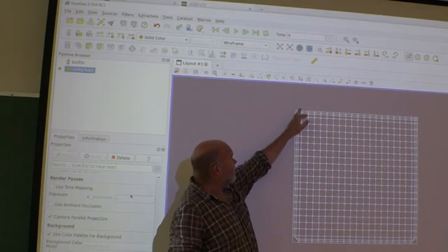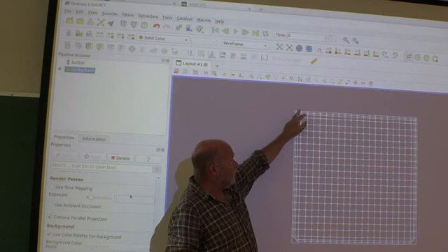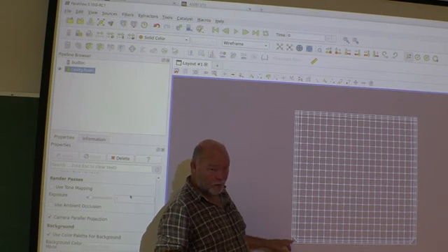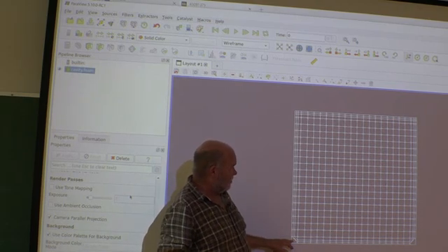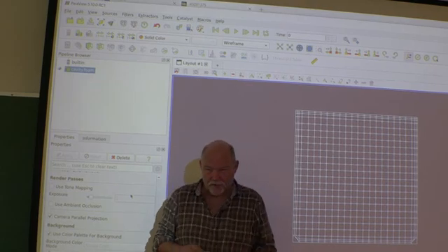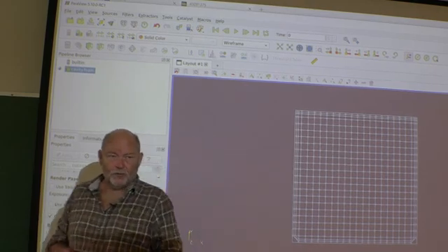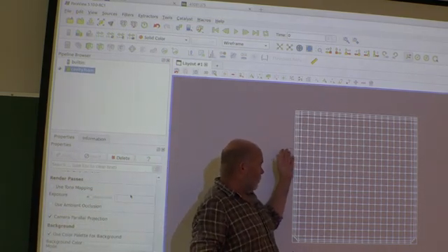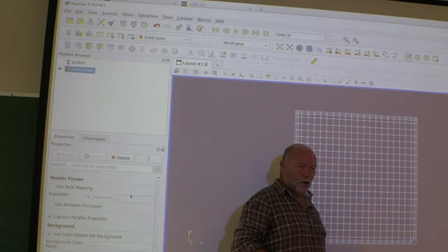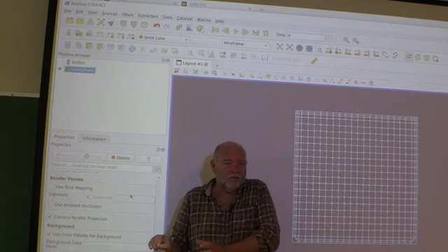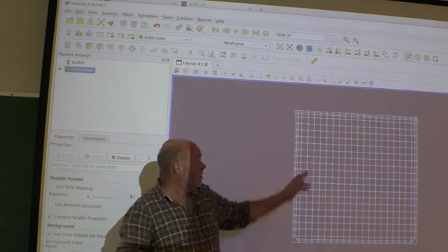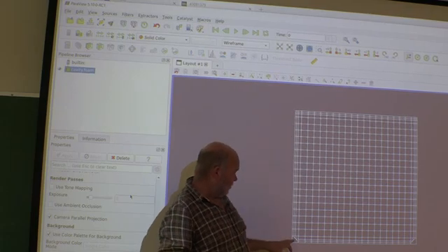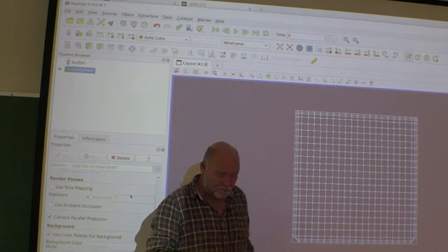But look at how he has handled the small corners up here. Much better than what he does automatically down here. So hence, if you are going to use this refine wall layer, then I will recommend you have top wall, left wall, right wall and bottom, and do them one wall at a time. Then he will handle such corners much, much better, instead of doing something really messy down here.